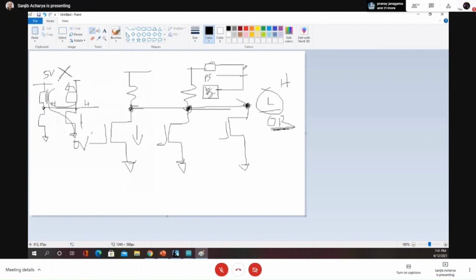All these will get ORed and will go to your microcontroller, right? In this kind of configuration you need to OR the outputs, and that is called open drain. Open drain configuration is recommended.